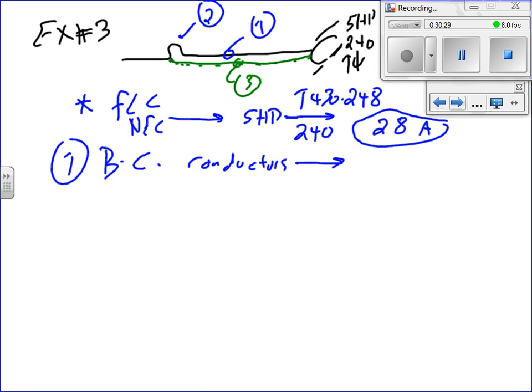Very good point. The table voltages, guys, are slightly less than the nominal voltages. There are two types of voltages they use in the industry. The nominal voltage is 240, 480, 208, and then there's the equipment voltage. That's confused people. The manufacturer designed the equipment to work at a slightly lower voltage because of the voltage drop.